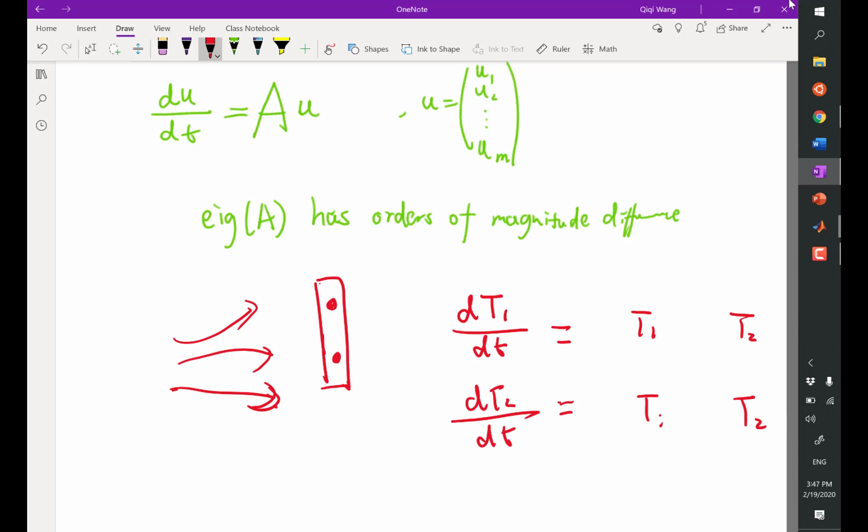The result is you're gonna have two parts, right? One part is due to the heat from the air. That coefficient is gonna be normal. It's gonna be whatever we derived on the first lecture. But you are gonna have another component that is due to the heat transfer between these two parts, and that is going to be very large,